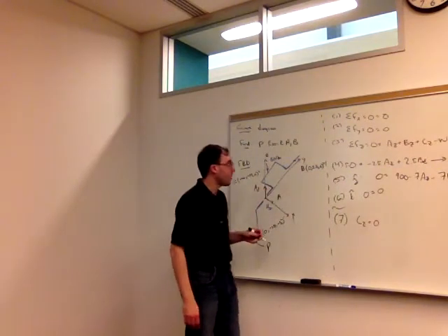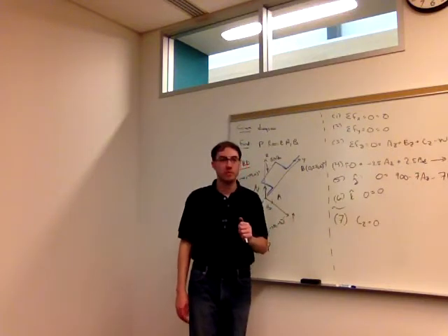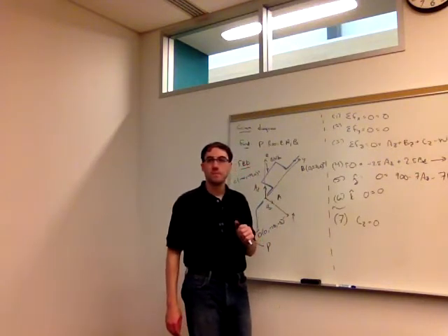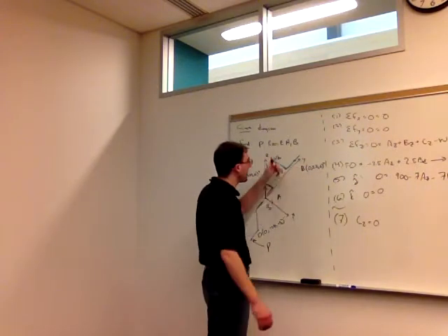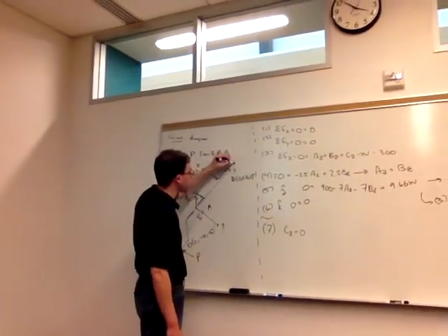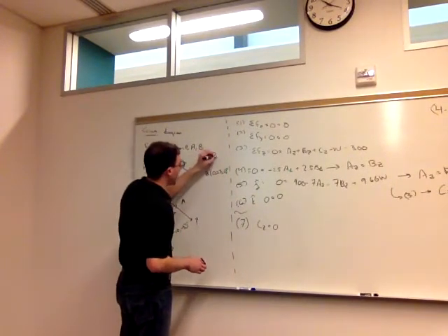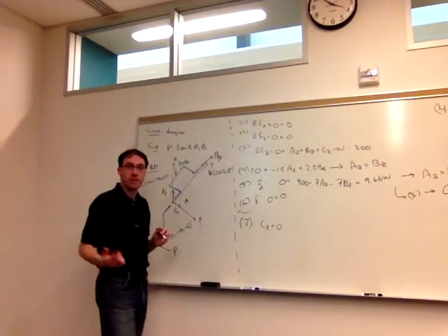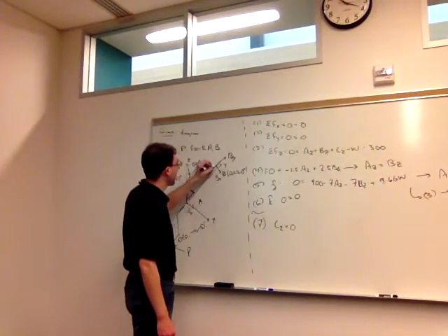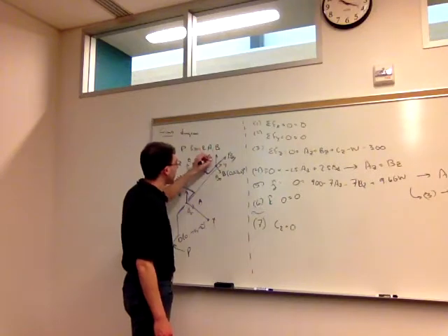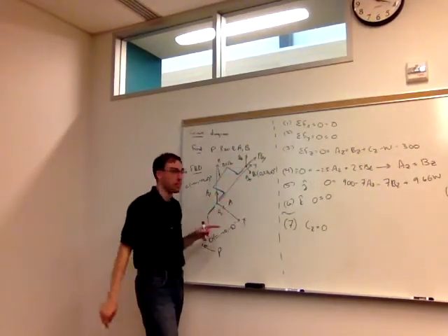And then at B, what are the reactions we have at B? What motion's prevented? Right, so B is the thrust bearing. So the shaft cannot move in its longitudinal direction, which is the y direction. So we'll have a BY. And it can't move perpendicular to its longitudinal direction, so we can model that as a BX and a BZ. Again, these two bearings are properly aligned, so neither one exerts a couple on the shaft.